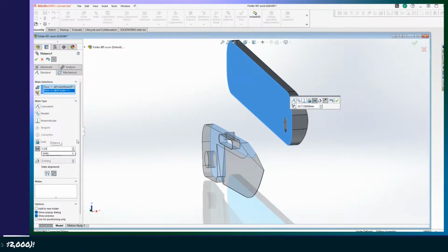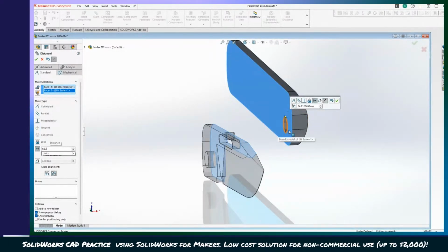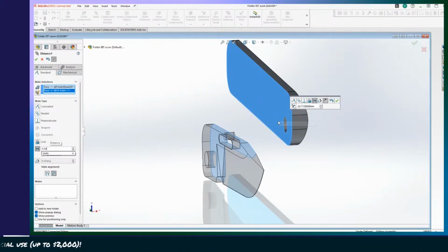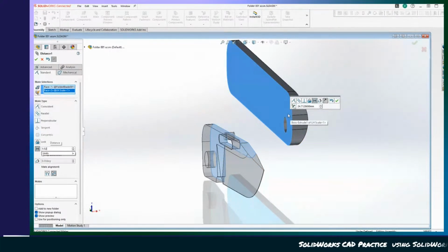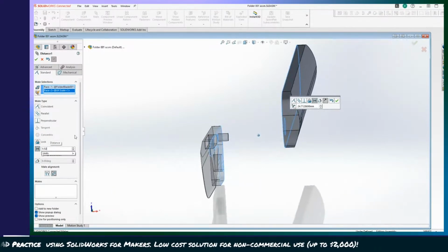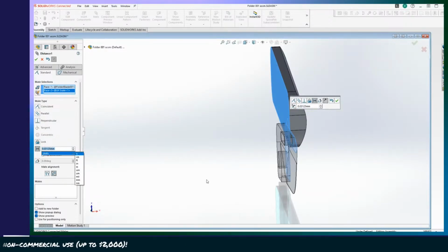And the reason for that is because I'm going to use 1/16 inch bearings. So I'm going to put a 1/32 of an inch recess in here, or more than that. But I'll put a steel washer in the titanium scale, or whatever this scale ends up being, so that the center of the bearing is even with the surface of this. So half of that distance is the distance I want to this blade. So I made that 1/32, and if you do that, it automatically changes it to a fractional.